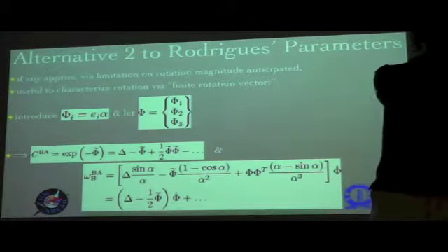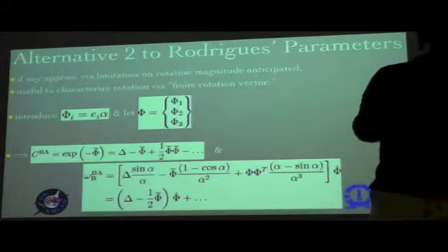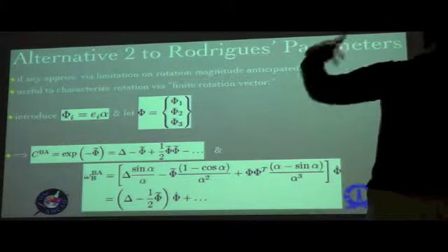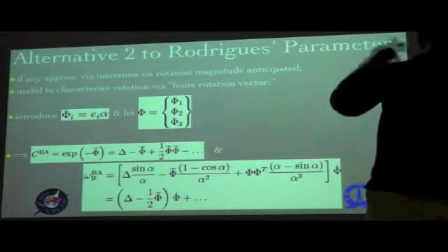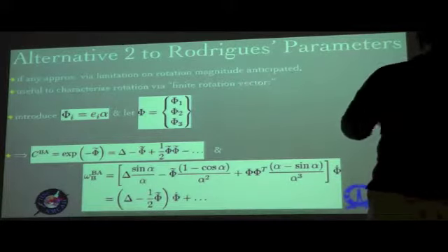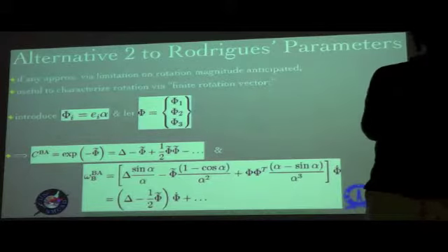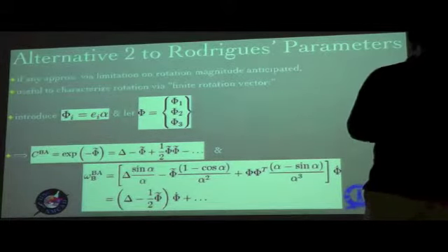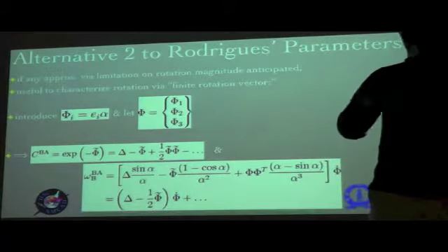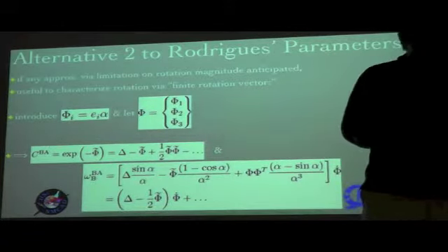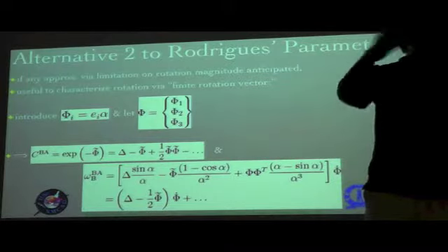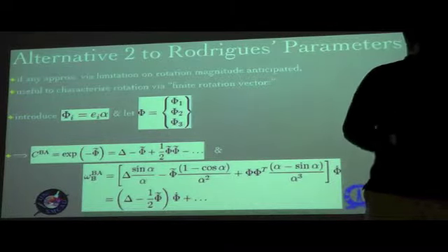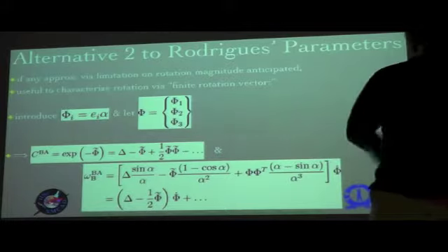Yeah, in the case where you had, let's say, that definition as 4 tan alpha by 4, then in such a situation you have the singularity at 2 pi, and that's something which is quite reasonable even for the rigid body like rotations of the cross section. But what I'm talking about now is something for much smaller values of the angles, not even pi or 2 pi, but much smaller than that. So these are things which cannot be used for rigid body like rotations of the cross section.